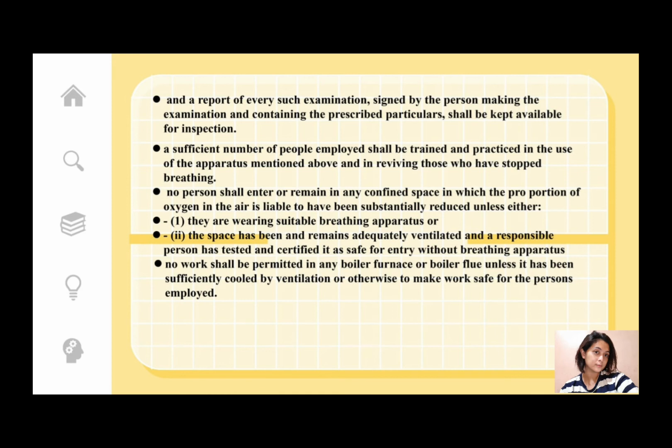No person shall enter or remain in any confined space in which the proportion of oxygen in the air is liable to have been substantially reduced unless either, one, they are wearing suitable breathing apparatus, or two, the space has been and remained adequately ventilated and a responsible person has tested and certified it as safe for entry without breathing apparatus. No work shall be permitted in any boiler furnace or boiler flue unless it has been sufficiently cooled by ventilation or otherwise to make work safe for the person employed.